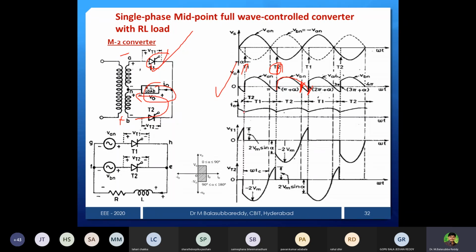So the current will start rising up to pi, then decreasing, then again the thyristor is conducting, then decreasing. Whether you want to maintain this magnitude or start like this, both are correct. I will draw the current waveform like this also. Starting at 0, because of the large inductor it will maintain like this; otherwise you can start at 0, reach the maximum, then decrease to 0, then rise, decrease, rise, decrease, continuously. So this is the current waveform. That way also you can do it.